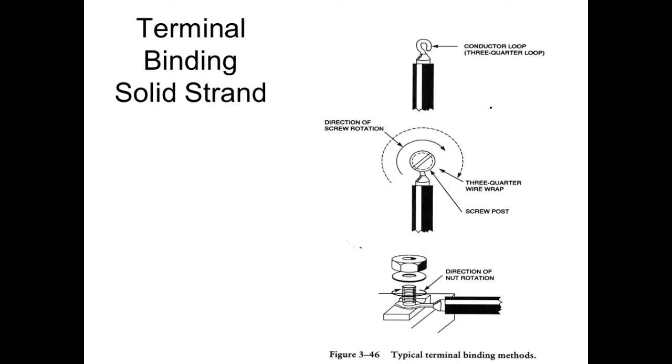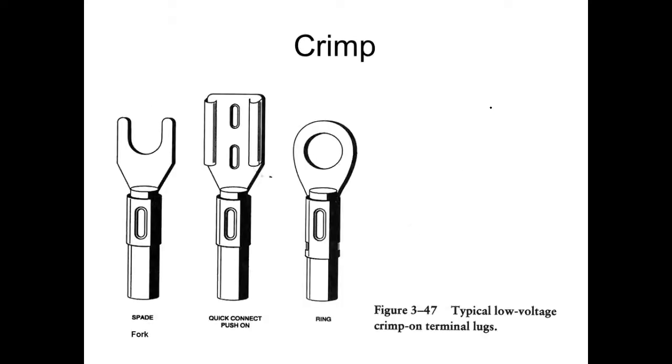But it's not flexible, right? The biggest advantage of stranded is a lot more what? Flexible, but it wants to bird cage all the time. It wants to come out of those spirals. So that means usually when we start working with stranded wire, we're going to have to terminate it with terminals, either solder terminals or what? Or crimp terminals.